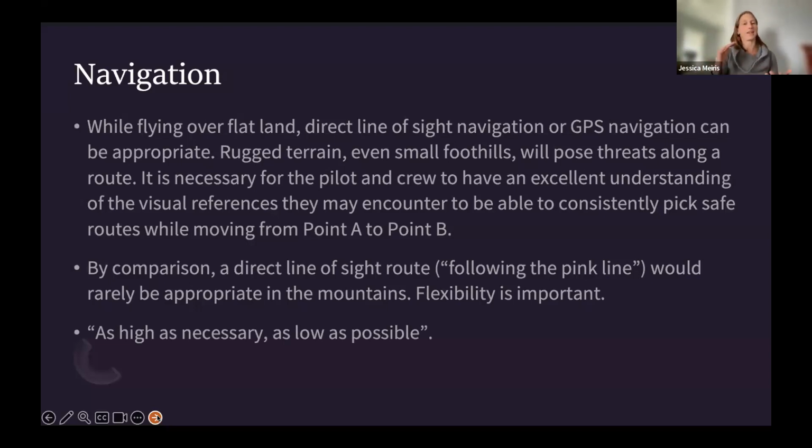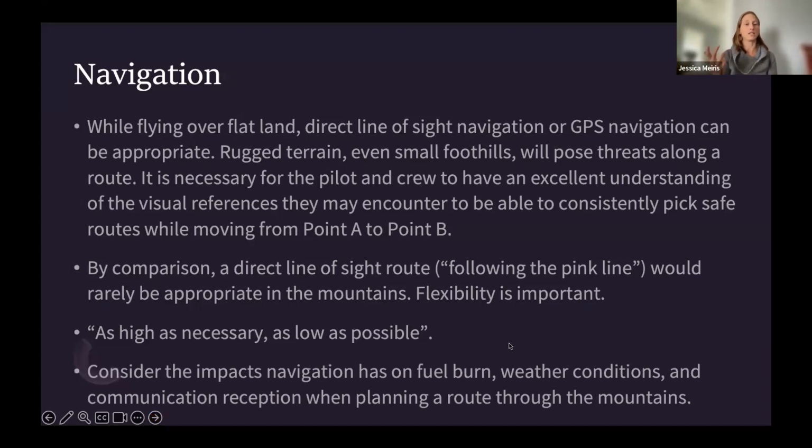Generally speaking, fly as high as necessary, however, as low as possible. And you might be thinking, why as low as possible? Well, low is often a way to stay out of things like mountain wave turbulence, rotor clouds, or high winds aloft. Being close to the terrain does offer some protection sometimes. However, we also want to fly as high as necessary to keep us away from, and situationally aware of, that terrain. And lastly, consider the impacts that the navigation has on fuel burn, weather conditions, and your communication reception when planning a route through the mountains.